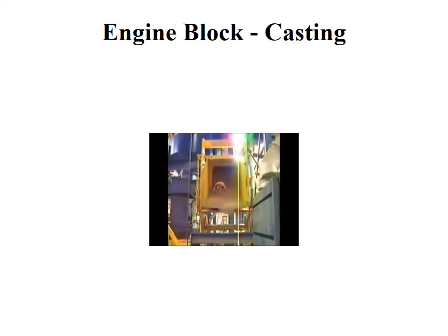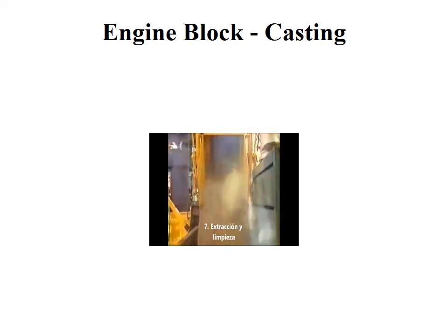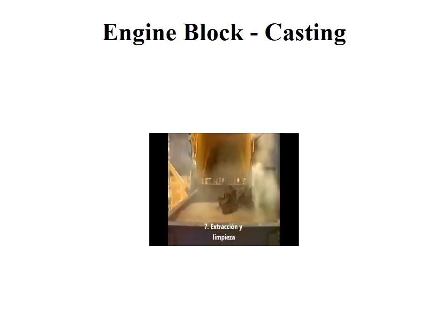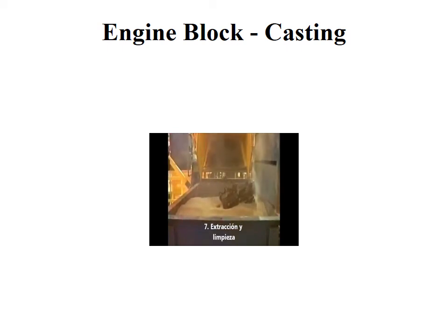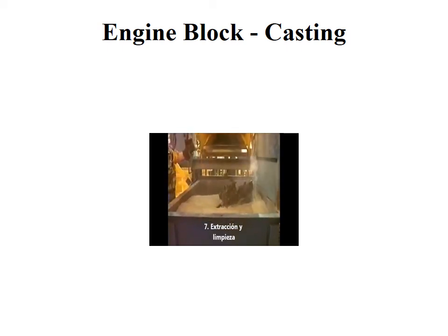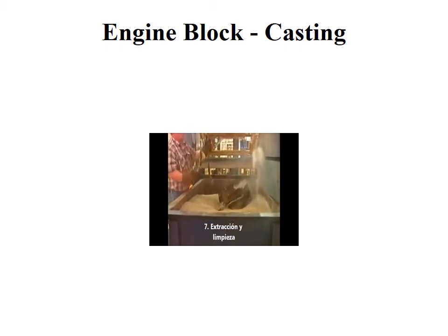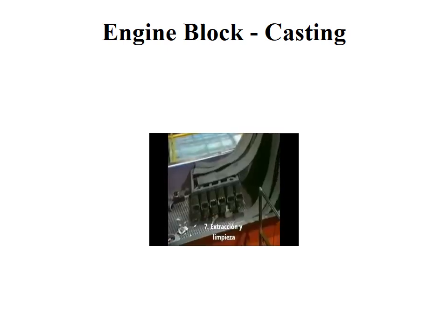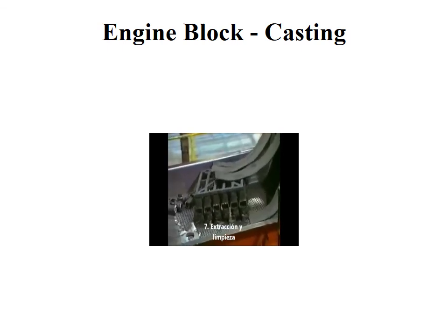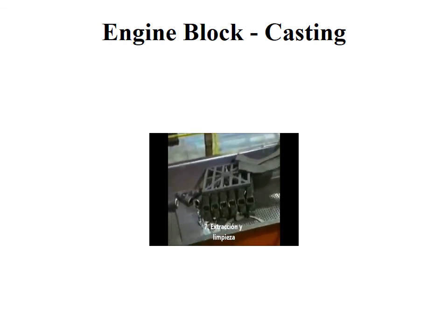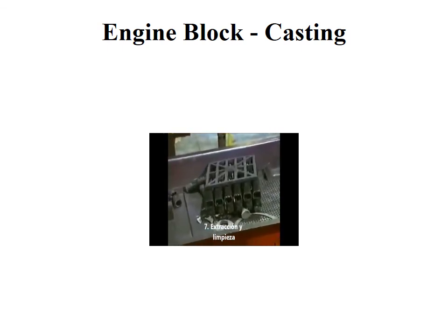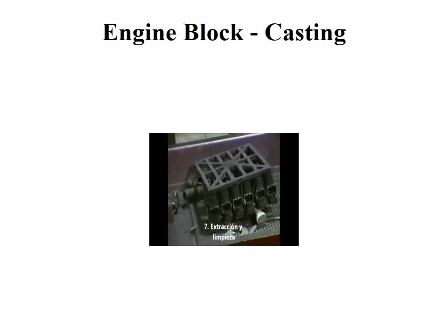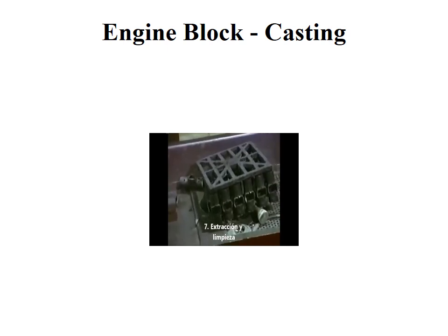After the poured cluster is allowed to solidify, the flask can be simply tipped over and the unbonded sand flows out. No additional violent shakeout or core removal are necessary. Because the foam pattern is left in the mold, no parting line is needed. This allows orientation of the casting to be more flexible and permits clustering, which produces more parts in a given mold area. More parts per mold means higher production at slower mold per hour rates.